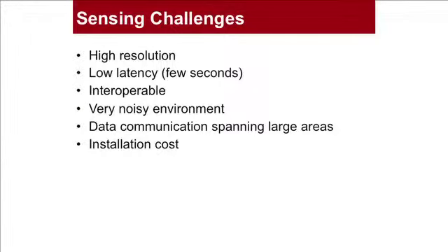So what are the sensing challenges in general for all of this sensing? The first challenge is that since at every second, every millisecond, we need to make sure supply is equal to demand, we need to measure everything at a high resolution. That's the very first challenge, and that's an electrical engineering requirement. It's not a requirement of the markets, it's not a requirement of the utilities, but everyone who operates the grid knows that for making sure at every millisecond demand equals supply and being able to control the demand or the supply, I need to measure what's happening, and that means high resolution.